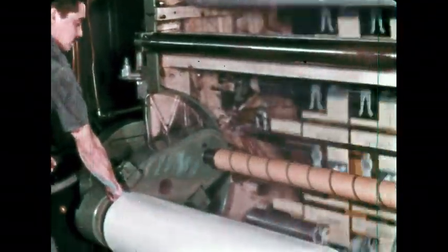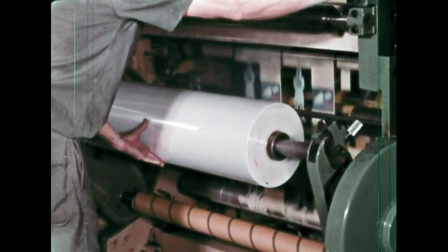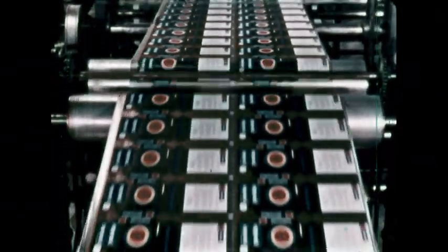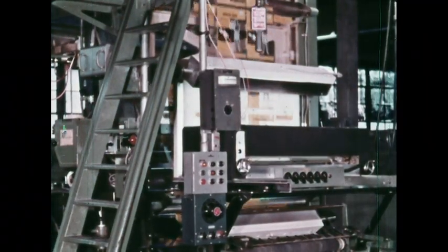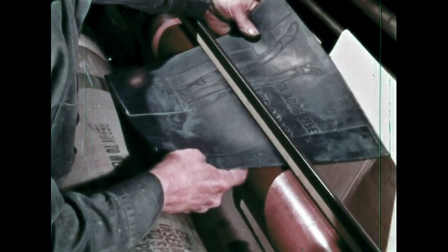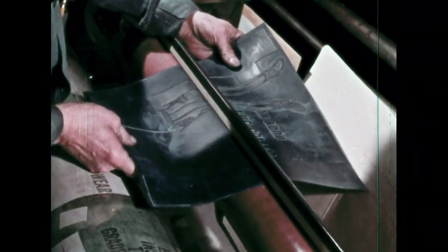Intaglio or relief are generally used on transparent, flexible materials for packaging, such as cellophane, or for labeling or packaging materials such as metal foils. Any of the gravure methods will give the thick ink film that these materials require to produce fine quality printing. But flexography is the only relief method for flexible packaging. And of course, the big advantage of flexography is its use of flexible rubber plates, which are cheaper and easier to make.